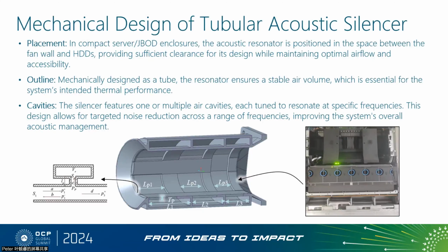To achieve this, the acoustical resonator is strategically placed in the gap between the fan wall and the HDD. This placement is crucial as it allows for sufficient clearance for the silencer design, while also ensuring that the airflow remains unobstructed and the HDDs remain easily accessible for maintenance.